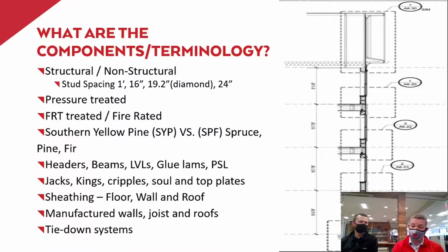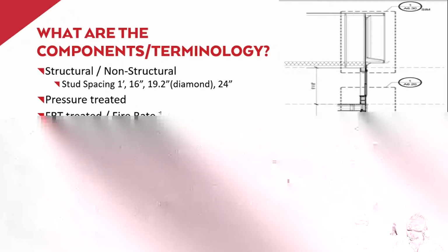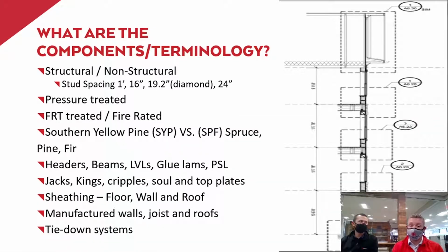Furthermore, if you have an astute inspector who sees, and the inspectors are looking for this now, that it's supposed to be a PSL, regardless of how many 2x4s you put in that location, it's not going to pass. And a lot of times they're put in weird locations, like in tub chases or in places that are hard to get to. So if you have to go rip those out at the end of the day, it can just be a nightmare to put in the right thing.